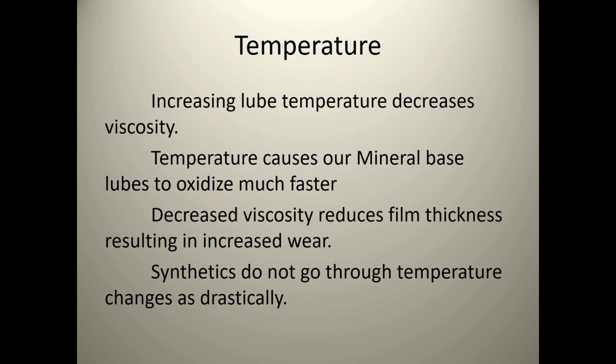Now, one of the nice things about synthetics, and one of the benefits of synthetics, is that they don't go through the temperature changes and viscosity change as much as mineral-based lubricants. That's why synthetics perform so much better, and you can use them over a wider range of temperatures because the viscosity doesn't change as much. Synthetics are much, much better in hot, high-temperature applications in your facility.